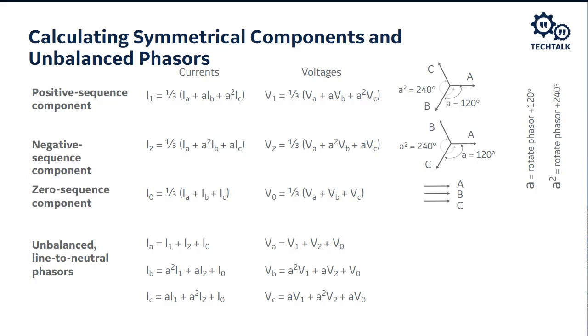If we're in a protective relay situation, we want to calculate fault currents so that we know what the relay is going to see. But this goes even beyond relays, because I might want to calculate these fault currents for the purposes of determining if my breaker duty is going to be exceeded.